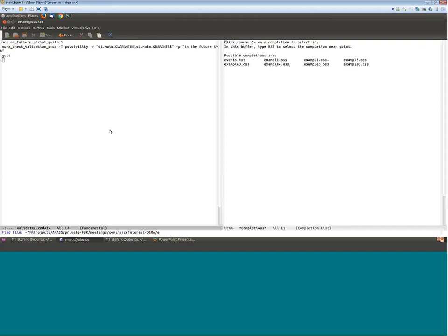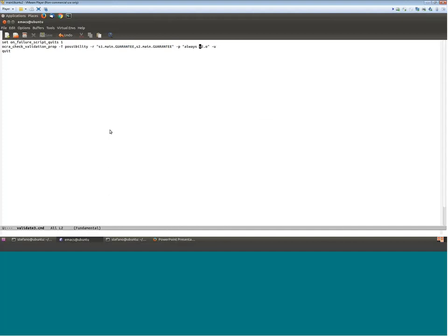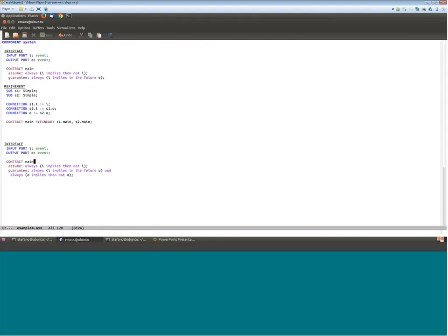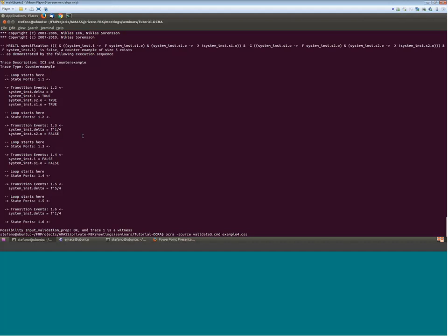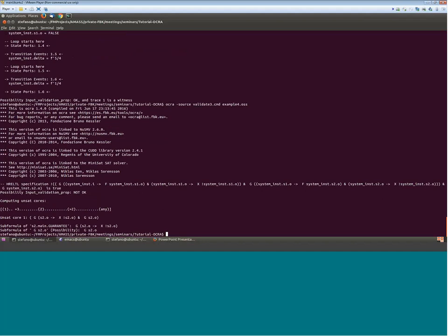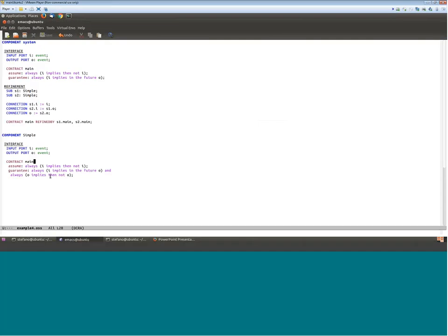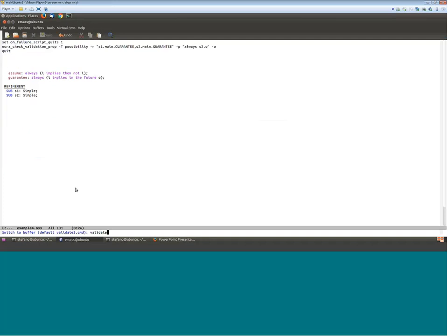And there may be cases in which the scenario is not compatible. So, for example, here I'm checking if these two guarantees are compatible with the scenario in which always there is an input, but in my last example, if you remember, I specified that we do not have two consecutive outputs. So in this case, the tool will say that this is not possible, and moreover we will provide an xSAP core showing the reasons for inconsistency. So in particular here it shows that this part of the contract is inconsistent with the property specified here.